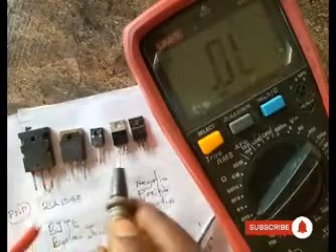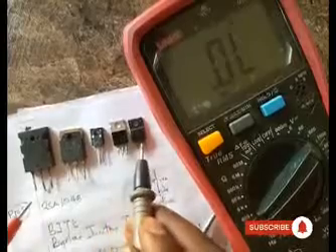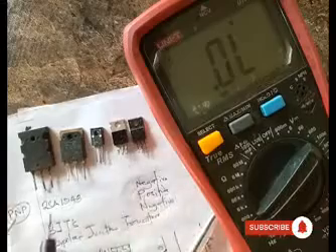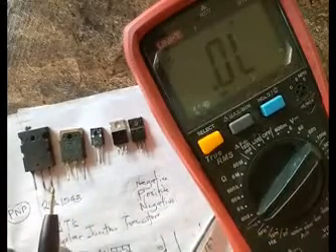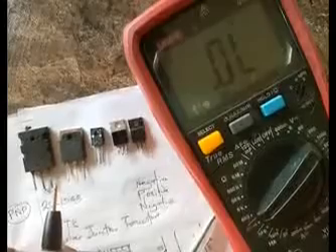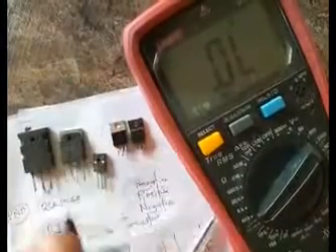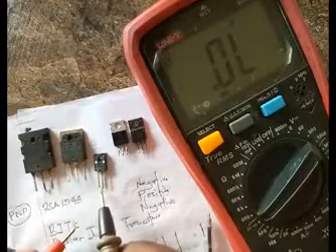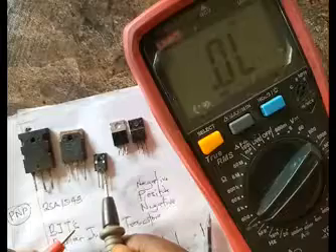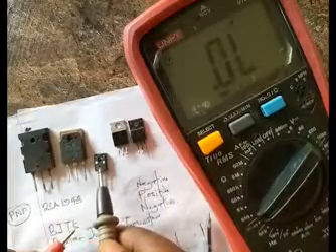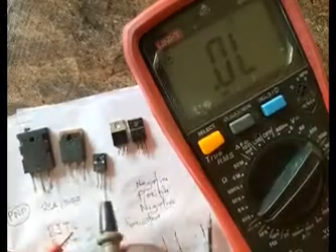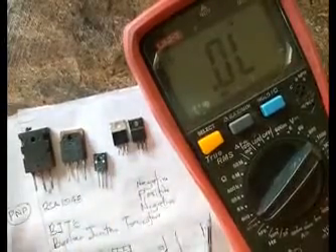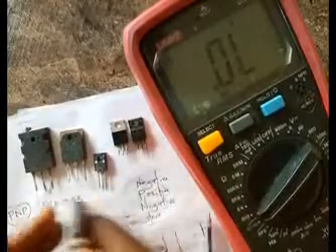All right, this one and this one have the same pinout. Okay, I'm going to test these two, and then we'll call it a day, so you can digest what we have already talked about. Now for this one, I already checked the data sheet, okay, and I know that this is the collector and this is the emitter, and this is the base. You see that the pinout is now different. So this is the base for this one, this is the collector, and this is the emitter. It's like you are reading it backwards. This one you are reading it this way, and for this you're reading it this way.